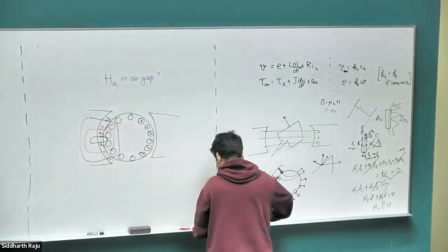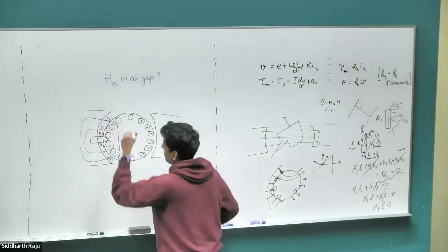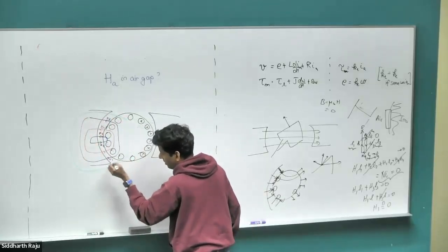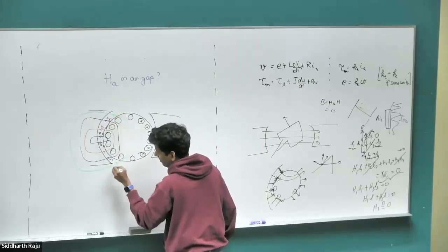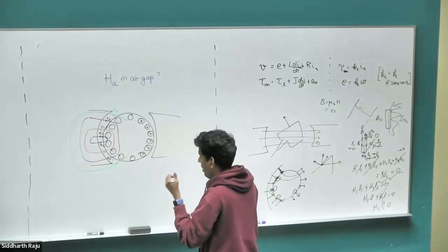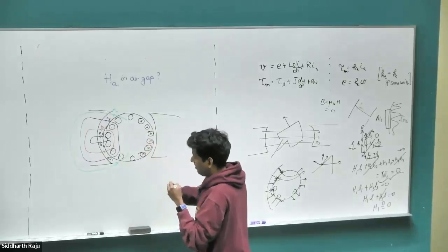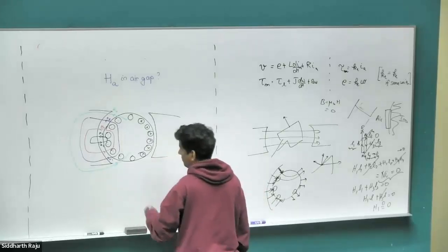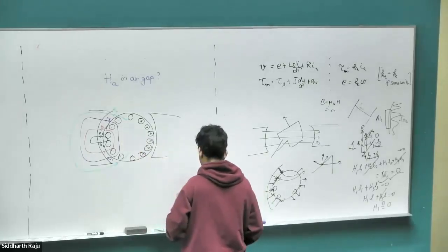And finally, again, it should always be perpendicular, even if my drawing doesn't look like it. Just remember that it's perpendicular. Of course, that does change when the core starts to saturate and it starts to behave more like air gap, in which case the perpendicular constraint starts to disappear.